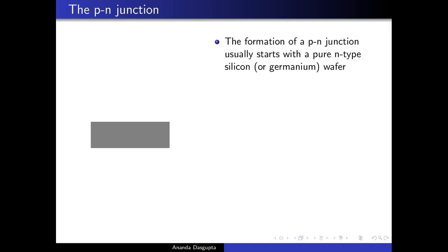That can be controlled by both the density of the vapor that you use, also the time of the exposure, and all of this is a very critical industrial challenge to be able to do in a very nicely controlled fashion. But because we are just learning the theory of this, we can be glib and say all you do is take a piece of silicon wafer, put it in some pentavalent impurity vapor, and that vapor permeates inside and you get an N-type wafer starting from an intrinsic wafer.